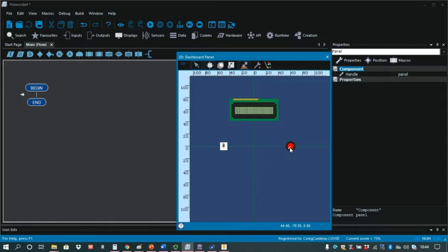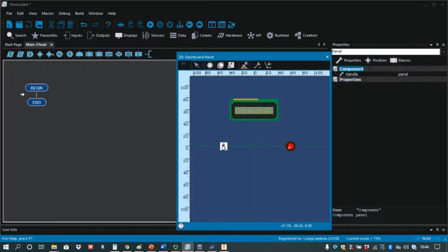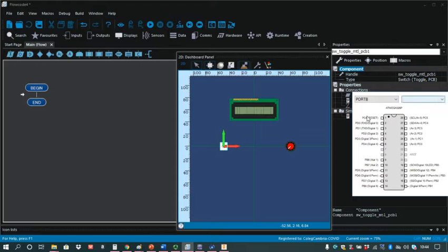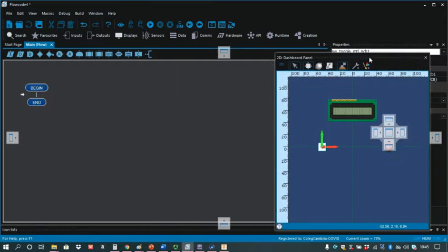When I say we'll put it to one side for a moment, that should be on AN0 for an Arduino Uno. You could use AN1. They're both analog inputs on an Uno, but they're the only ones. And on this one, this is now on A0, so that's going to conflict because it's the same one. So I'm going to use a port that I know isn't used, so I'm going to put it on C0. Okay, so that now is the active line for C0, and that's the active line for A0.